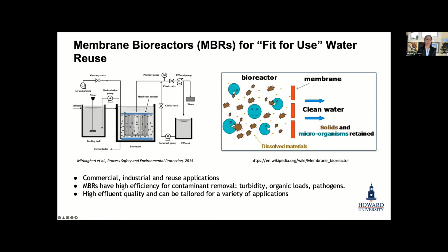You have the membrane here, you have your effluent or your suspended microbes in your bioreactor, and the membrane just filters them. So think of it like a conventional activated sludge process where the membrane is the filter. And a membrane is a much more efficient filter than some of the filters that are typically used in a conventional activated sludge system. And so given that the membranes can be fit into a smaller footprint often, and you get more efficient removal of a lot of contaminants that may otherwise go through your filters.